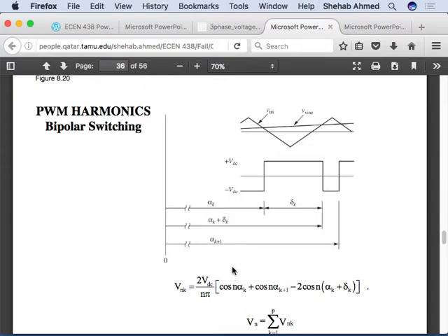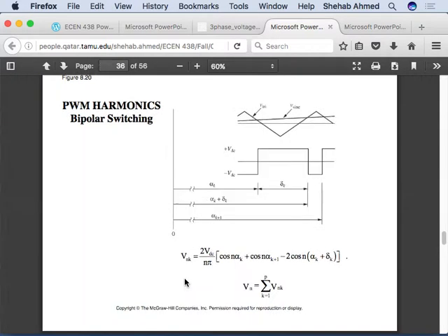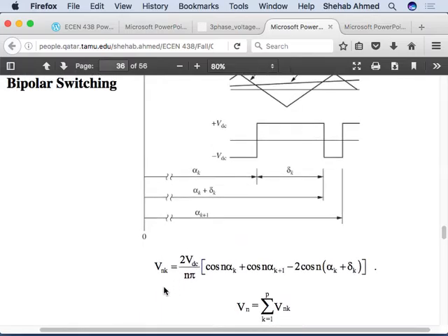Okay, so this single pulse K is contributing to the harmonic content of the waveform, whose nth harmonic is Vn. Right, so I have a waveform that has many harmonics, V1, V2, V3, V4, V5, whatever it is, and I would like to find the Fourier series. So I'm using each pulse to find the effect of every pulse on the Fourier series of the waveform.